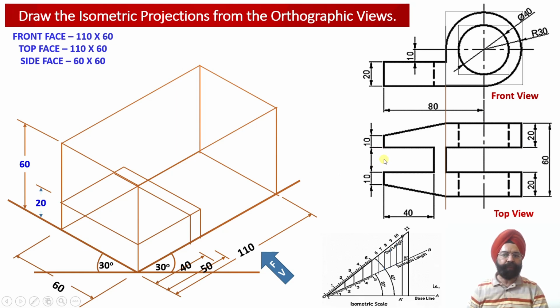so that from this point we are able to obtain this rectangular slot located at the center of the solid alongside the width of the solid, and then a 10 millimeter offset corresponding to this web surface, 10 millimeter offset towards the front side corresponding to this portion of the web we are going to locate.